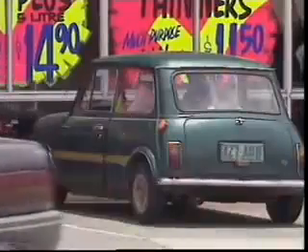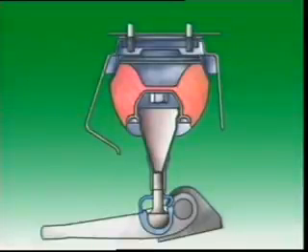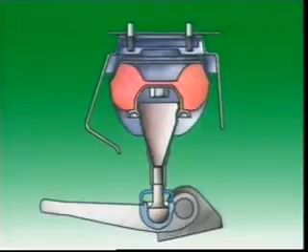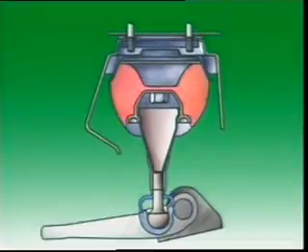The stops can also be shaped to provide an auxiliary springing function, increasing their resistance progressively with suspension contact. Some vehicles use rubber as the main springing medium. This rubber cone is this vehicle's main suspension member. Increasing the load on the suspension causes the cone to act like a spring being deformed. When the load is removed, the rubber's elastic properties tend to return it to its original state.